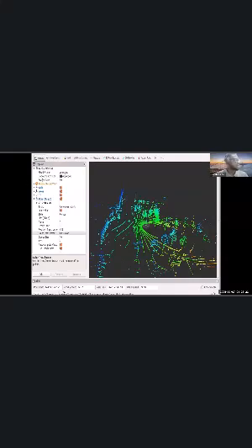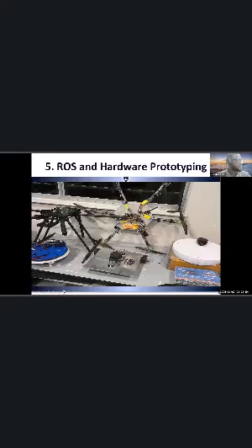You see the different topics you can be visualizing there, and there are different frames: a TF frame, the point cloud, and we'll do that later. We'll do this together and see it. This is my project I was able to work on. I did SLAM, which is simultaneous localization and mapping, for the robot to be able to move by itself autonomously in my school's cafeteria, and it was successful. I got about 95% accuracy working on this project.